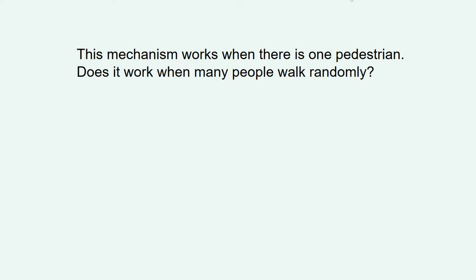But Mickey walks left, right, left, right. On the other hand, Minnie walks right, left, right, left. What would happen? Their lateral exciting forces cancel out, producing no force. We have a problem of phase difference.